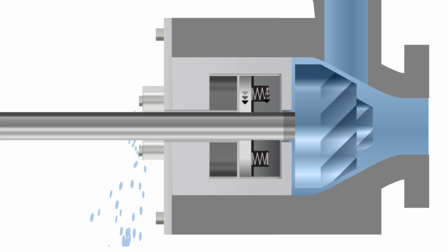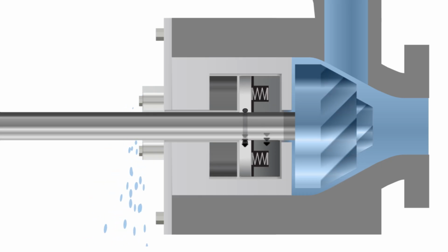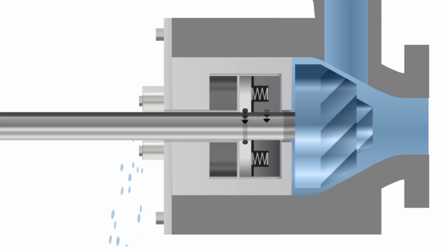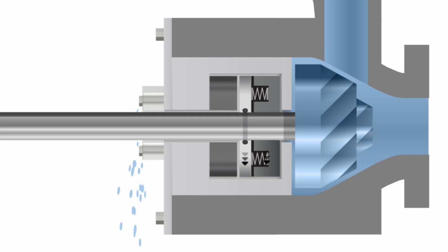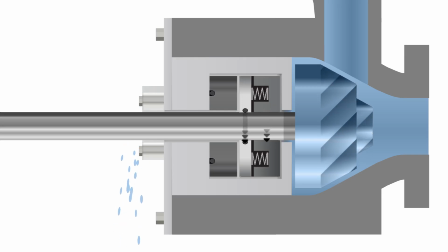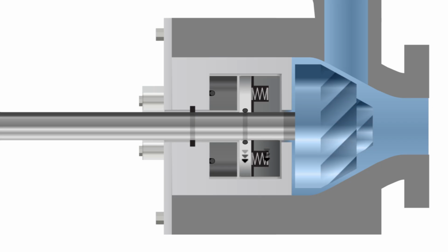The fourth component is the secondary seal arrangement. One seal sits within the rotating primary ring assembly, or face assembly, and prevents leakage along the rotating shaft. The second sits within the static mating ring, or seat, and prevents leakage around the mating ring. The seal is now complete, and the leakage has been contained.